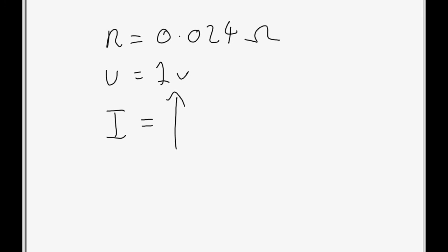In this case, we've got 0.024 ohms and a voltage of 1 volt, so 1 divided by 0.024. Current is going to be 41 amps. That's a serious amount of current flowing in a circuit. That's going to be almost all your source zapped instantaneously. If it's a battery, you'll probably explode the battery, or it'll be extremely hot, because you'll be drawing maximum current.